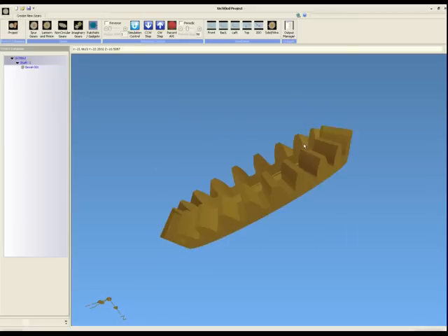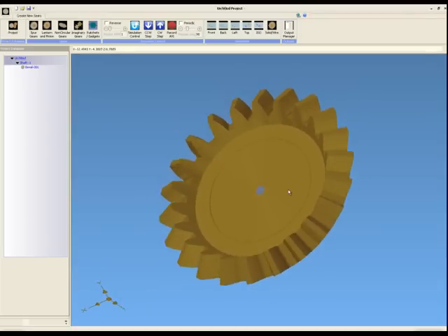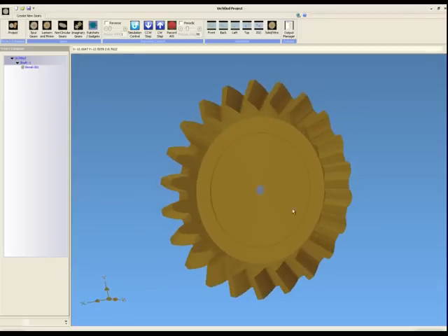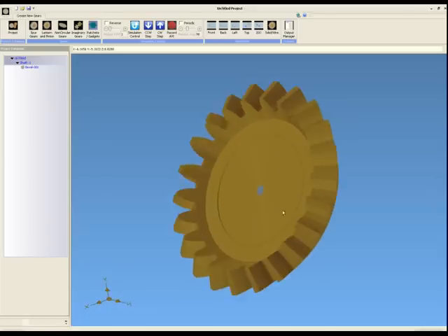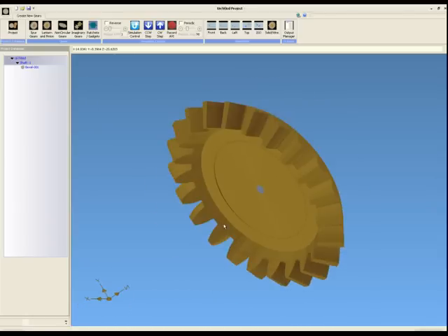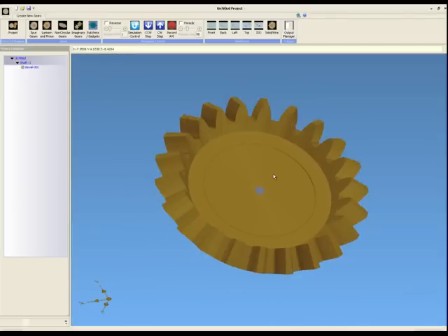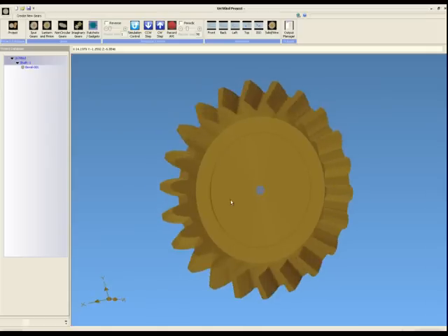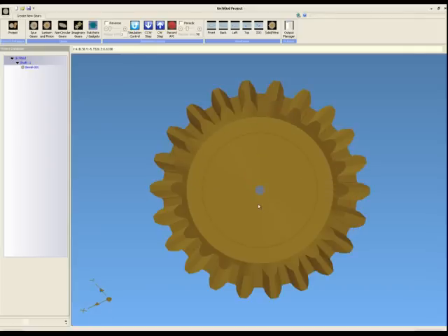This isn't terribly important to you. You can simply place them quickly. It affects the tooth strength. Normally you want to have a tooth which is thick enough to handle the torque that you're going to place on a bevel gear. Again, if you understand the issue of the strength or the torque of the teeth, then you probably already realize that the face width is important. So the setting of that gear thickness should become somewhat clear to you.